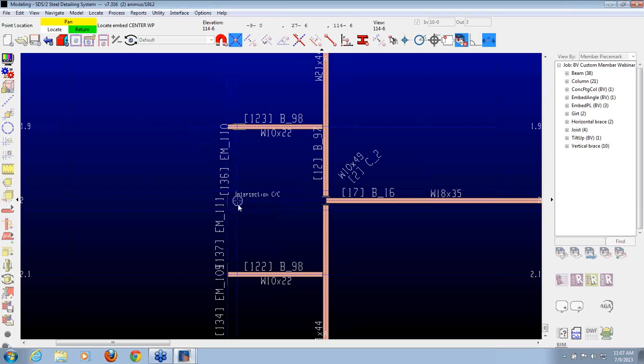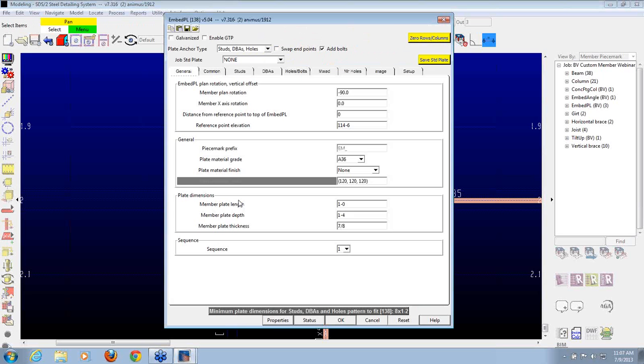This reference point is going to be just a single point. It's going to be the middle top of that plate. So if I select right behind it here, it's going to use that point as the top center of the plate at the back of the plate, which would be the side the beam will be framing to. So I can fill out all the information here.